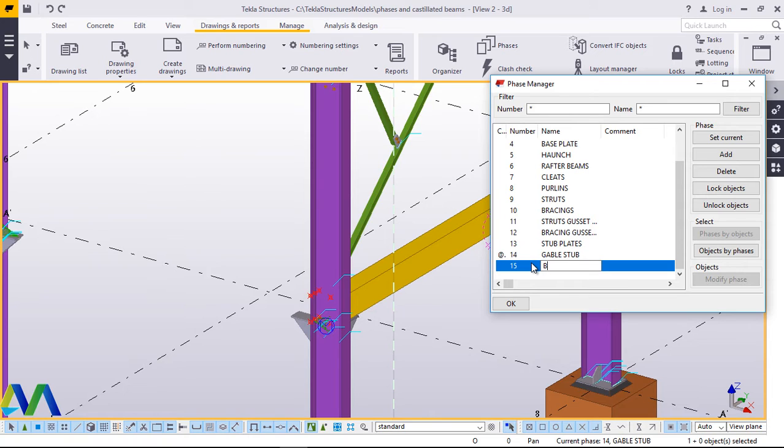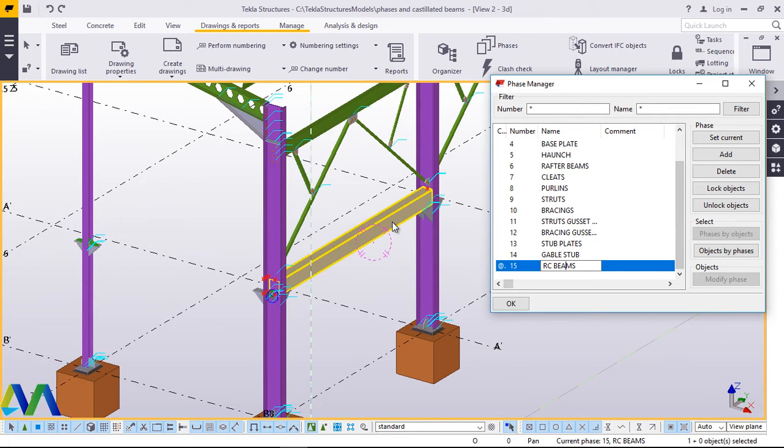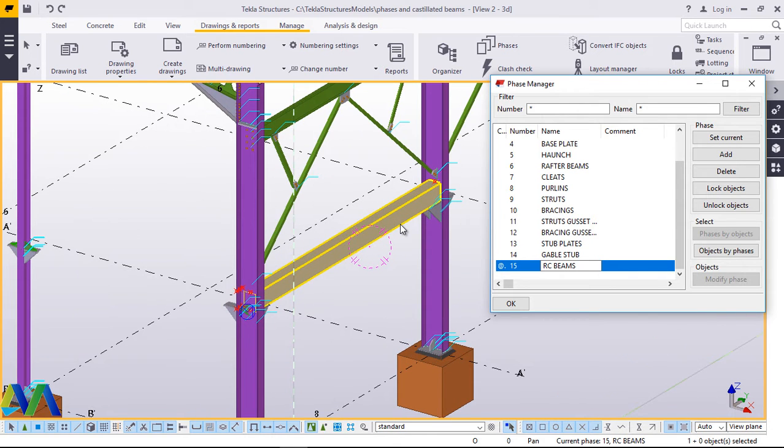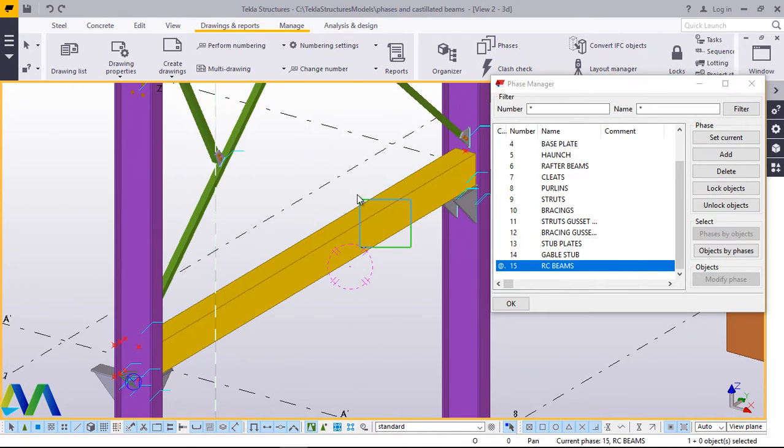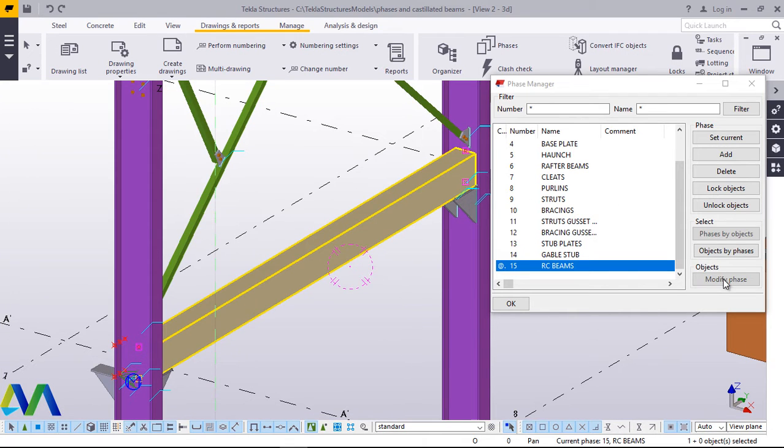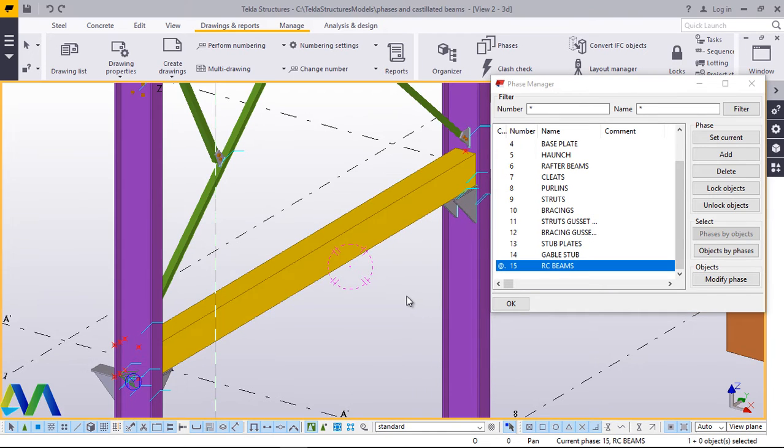I mean, right there, RC beams. Perfect. We'll make them current. We'll make this current. Then under RC beams, select the RC beams prior to categorizing or classifying them under face manager. Then I'll go ahead and highlight everything there perfectly well and come here and modify. Click that. Then click on empty screen, then come back and check whether what you've done is okay.